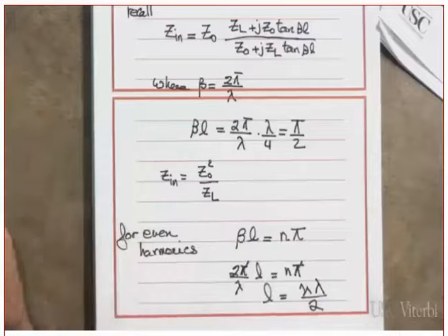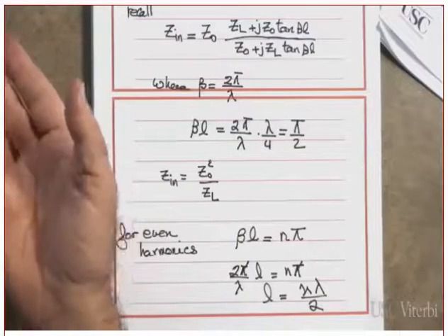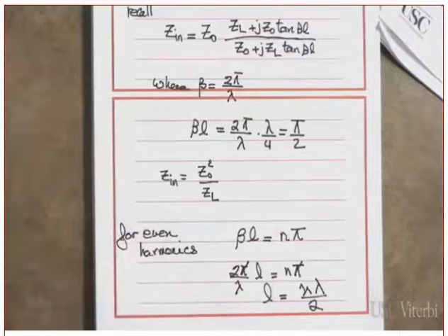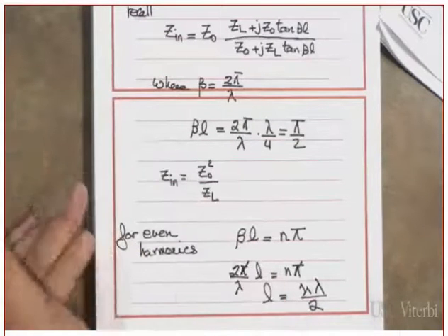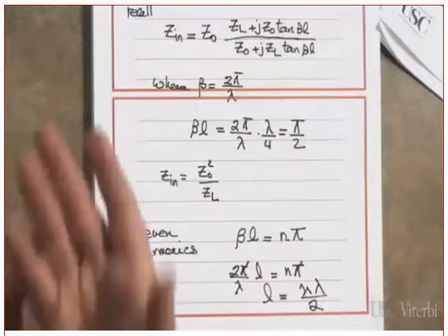One more time. Did the actual length of the transmission line change? The actual length of the transmission line did not change, but it is resembling a half wavelength rather than a quarter of a wavelength. Did you get this or not?